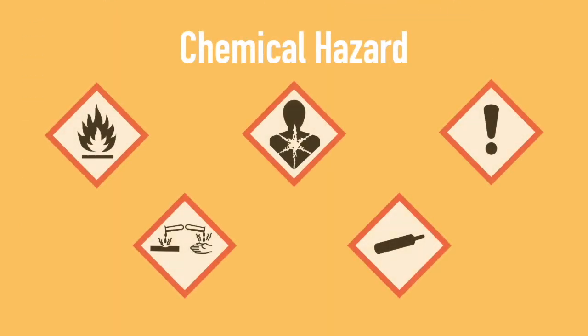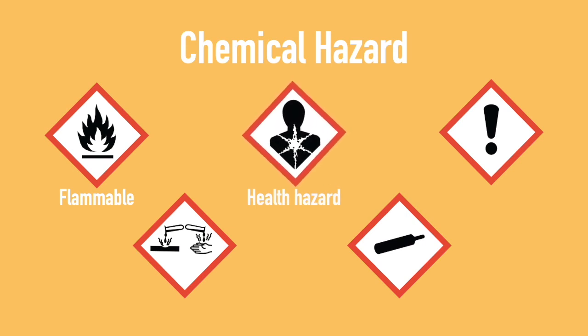The second hazard is chemical hazard. Most of the components in the stripper unit are flammable, which means they are liable to self-ignite when exposed to air or water. This is mostly due to their low flash point. The fire is followed by release of harmful gases which may damage human health as they are either toxic, carcinogenic, or mutagenic. Irritation is also present, which has immediate effect by irritating the skin, eye, and respiratory tract.